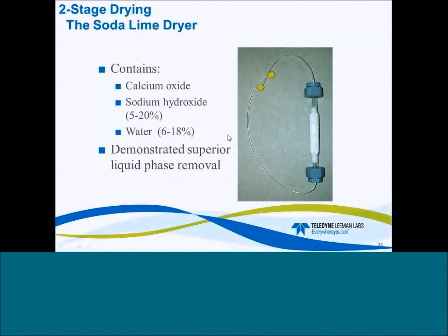One other thing when you use fluorescence that you need to be aware of is that molecular species will quench the signal that you achieve for a given concentration of mercury. So if you have water vapor that is passed through your fluorescent cell, it will decrease the signal that you see, and it can decrease it quite significantly.